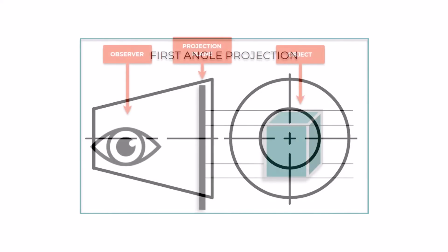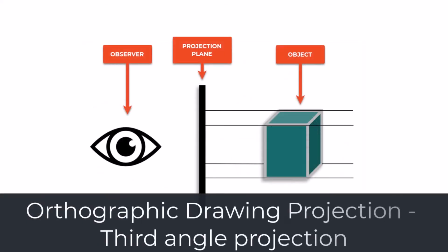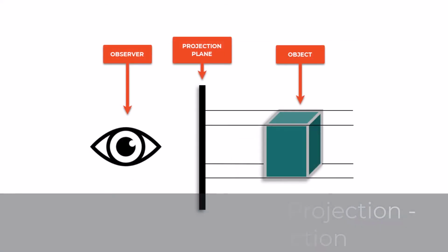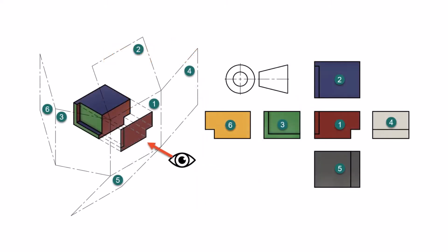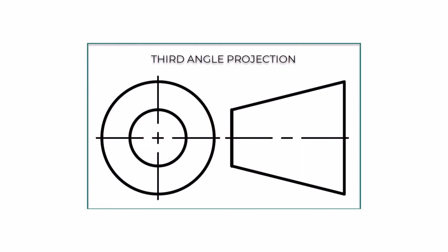5456-2-1996. Third-angle projection. In the third-angle projection, the object is positioned behind the projection plane. Every view is projected perpendicular through the object to the projection plane, i.e., the shape of the surface is parallel to the projection plane. Considering that we have 6 orthographical views, the projection planes of all views form a cube, and the inner faces bear the projected view. The third-angle projection is preferred in the USA. The symbol for the third-angle projection is defined according to ISO